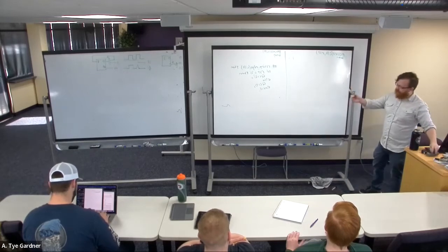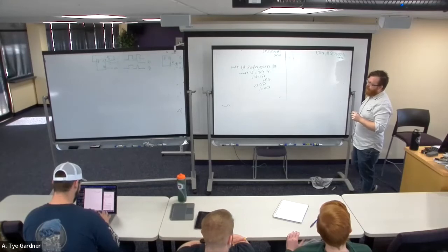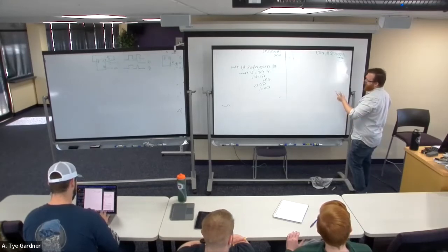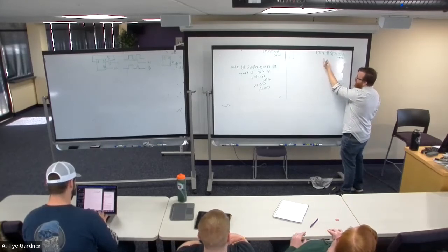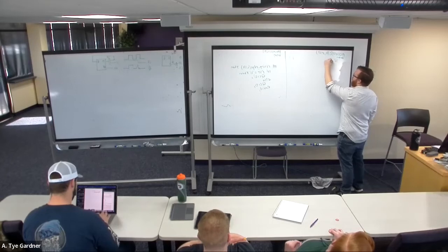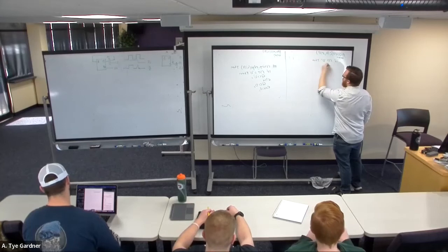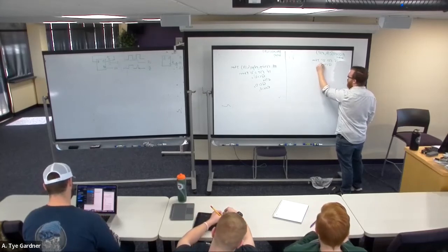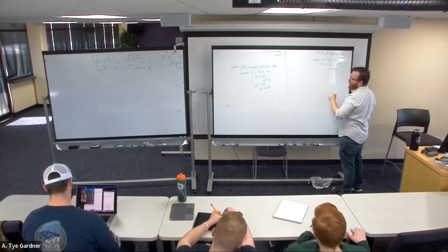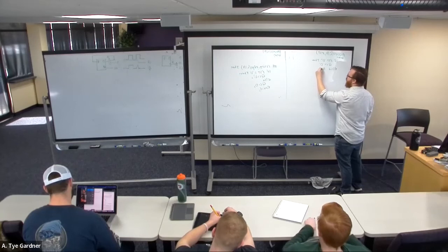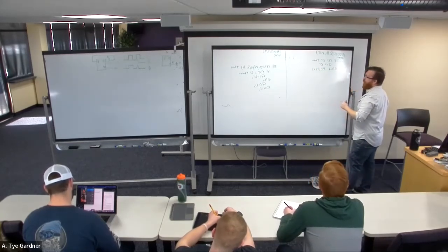So if I build that device, with asynchronous reset, I can do this a couple different ways. But an if statement is fine, right? I can basically say on the clock and reset, if reset is 0, that makes it active low, then Q gets assigned to 0. Else if rising edge of clock,